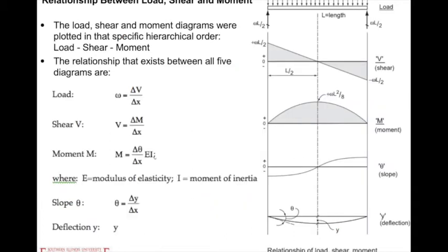So what it means, let's look at the entire picture. We follow this one and continue to look at the interesting observations. So this is the V diagram, this is the M diagram, this is a diagram of slope, theta, that's the deflection of this beam, and this is the Y, that's the vertical deflection of this beam. The change in shape looks like this, and this is the theta, that's the tangent to the curvature at any given point here.